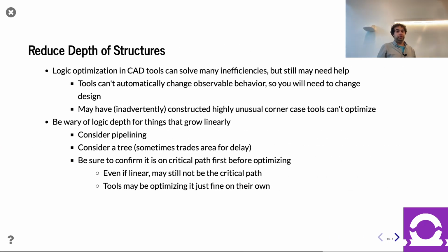So that was one opportunity. You know what? If you can just simply put some more registers in your design, let the tools do some retiming, or maybe put registers closer than they need to be. Another technique is to actually look at the logic and recognize that sometimes your logic can be made more shallow. Like I said, the CAD tools have their hands tied behind their back, in the sense that they cannot change the functional behavior. If you say I want A and B in Verilog, the tools can't give you A or B. That's not okay, so they're constrained by that.